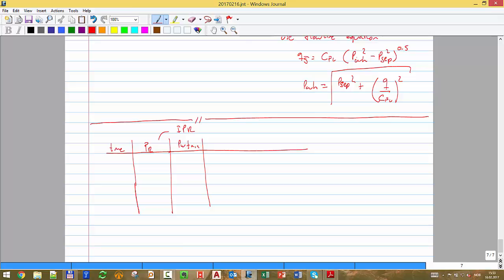But what do I have to do now on the basis of this new tool that I gave you? Assume Q gas. You first find the equilibrium. What is the equilibrium rate, right? So let's say I have PR, I have a Q. For example, I can assume a Q. And then with the Q, I'm going to calculate PWF, right? Then I calculate P wellhead available. And then I have P sep, right?